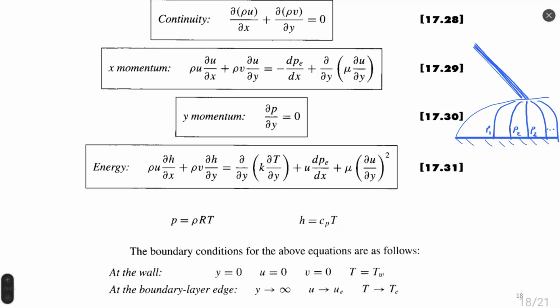This is how we can always understand that we deal with viscous flow. Once we see simulation of viscous flow and behavior of pressure inside boundary layer, this behavior of pressure will have always normal direction with respect to the wall direction. So pressure lines will be always perpendicular to the wall.